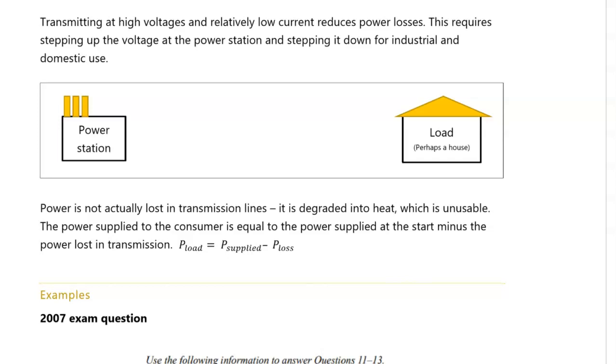Because we have the same power on both sides of the transformer because we're looking at ideal ones, the consequence of that is that the current went down. So increasing the voltage, the purpose of that is to make use of the fact that the current has the inverse relationship and will reduce by the same factor. That is going to be the big thing here. Okay, so how's that going to look? That means from the power station, shortly afterwards, we're going to put in a step-up transformer. Yes, I know my drawing is fantastic. So step-up transformer will increase the voltage and it will decrease that current.